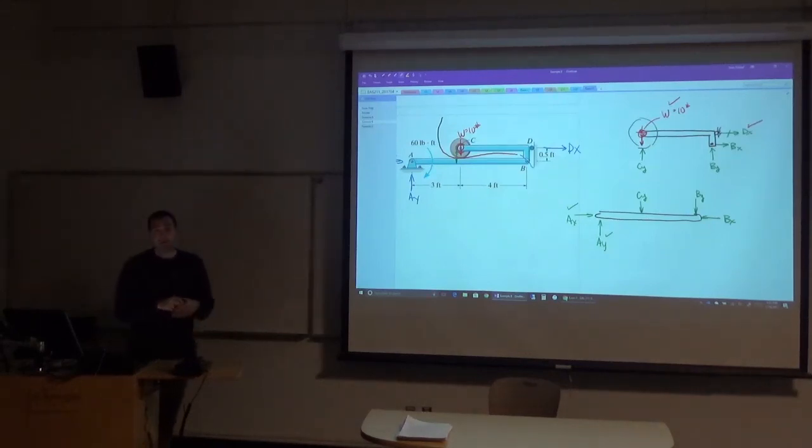This is kind of like our discussion about when we're looking at a beam and we make a section cut and we choose, say, the left side. I'm not ignoring all the loads on the right side of the section cut because they get implied in these support reactions right here. So like this support reaction AX and AY, part of that is due to the weight of that roller. So it's not like it doesn't exist, it's just that we're only looking at the effects of it as it gets imputed to point A.